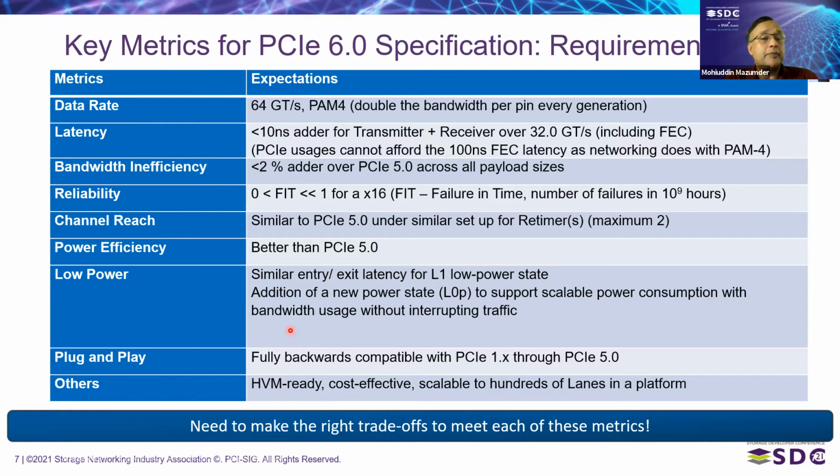Power efficiency needs to be better than PCIe 5.0. And in addition, for low power, all the features remain similar to previous generations. Entry and exit latency for the L1 low power state, but we also have added a new power state, L0p, which supports scalable power consumption with bandwidth usage without interrupting the traffic. So without introducing much latency, it provides another low power state.